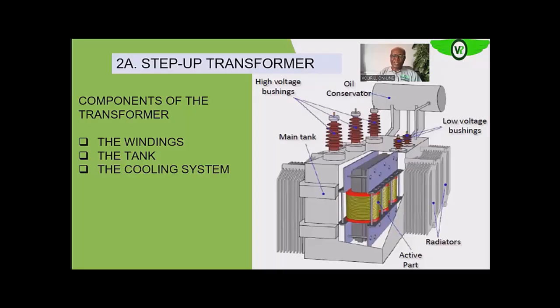So since we need to remove this heat, we need to have a system that will help us to do exactly that, and that is what the cooling system does. So the cooling system is a combination of the oil within the tank and the cooling fins, as we'll see later. So the heat generated around the windings,